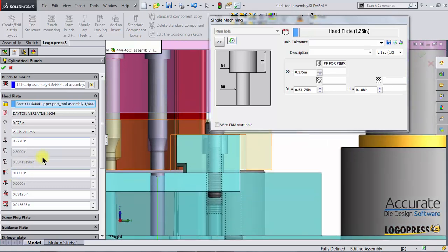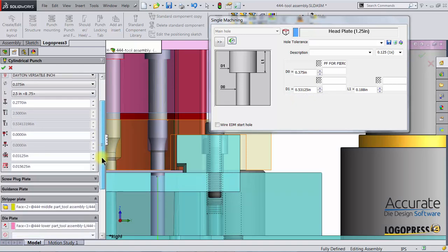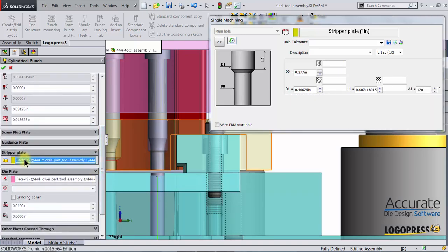And then I am going to select my punch length, which has already been determined. The point length is defaulting to what we had last used, 3/4 of an inch. That's fine. Then my point diameter is already set because I had populated the punch into this box. So I'll scroll down and put focus in the stripper plate box, and I'm going to add a 32nd to this diameter.